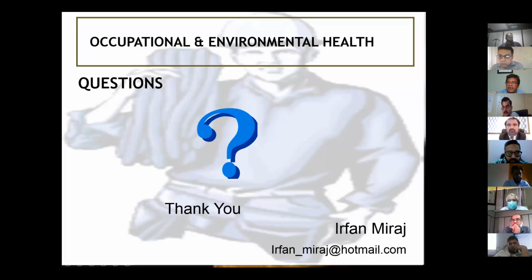Dryness, headaches, dizziness. Those are the basic tests that every consultant would come in and do. I showed an example of a classroom where carbon dioxide was not being controlled. It was 4,000 ppm for 3 years, and ultimately all we could do was reduce the number of students. The classes were reduced to 25%. But air quality is something which may not be defined.